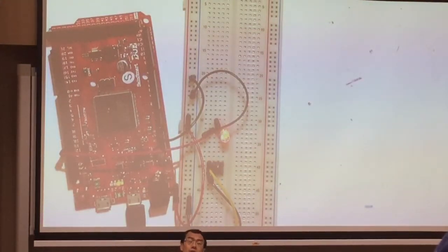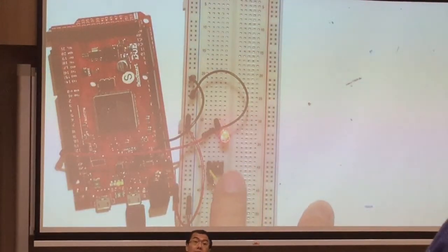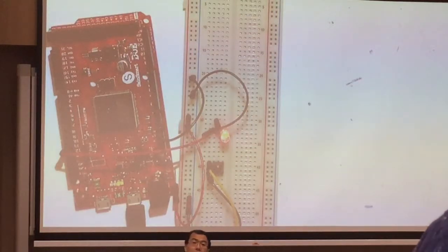the intensity increases. Again, the other point is, can you see the LED is blinking? No, right? Because the frequency is high enough, you won't notice. Now my frequency is 1 kilohertz, and our eyes cannot catch the blinking.